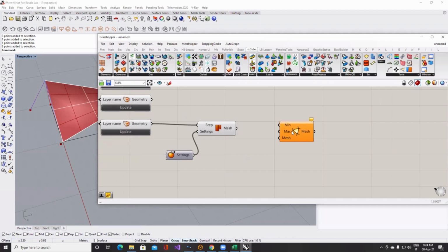The nice thing about this mesh tool here is that it will generate the finite element mesh. You know the difference between a normal mesh and the finite element mesh. Generally, when we use triangular elements, we want them to be more or less equilateral, triangles made by 3 edges with the same size. This is always a good way to go when we're running a structural analysis or FEM analysis over meshes. So large and skinny triangles are to be avoided because they make bad numbers at the end.